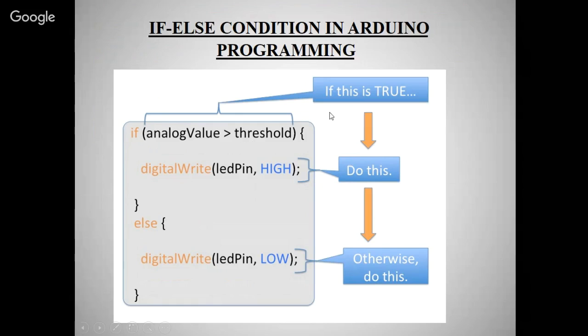The same we have used in this solar tracker: if the LDR1 value is greater than the LDR2 value, then it will rotate according to the values. It will try to track to increase the value and stabilize it, meaning the value on both LDRs will be the same. When the solar tracker is stopped in the stable condition, all the LDRs have nearly the same values, and until then it will keep rotating.